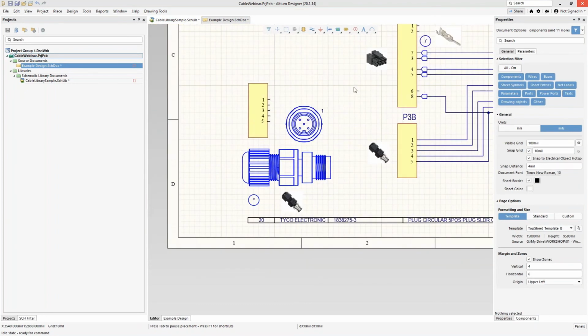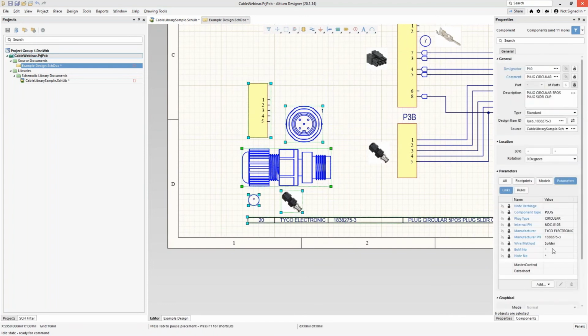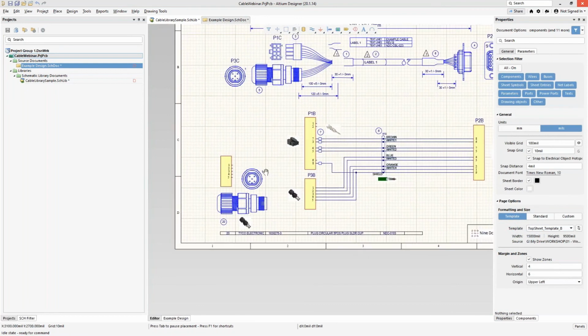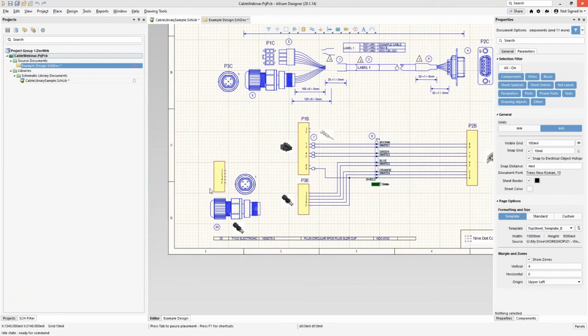So again, when you have everything here together, this is when you want to get everything fixed as one. If this is BOM number 20, then I'll click on this, and now all of these things have taken on that particular element of it. You want to fill out any of these other things here as well, so that once you're done and ready to scatter these things wherever they need to be placed, you know that they're all part of this, because trying to get them back together afterwards is a real big chore.